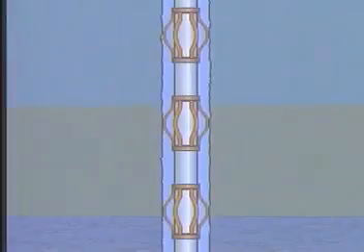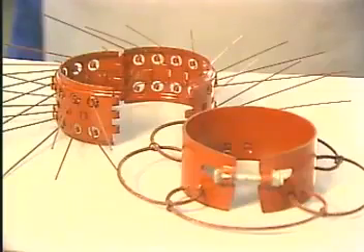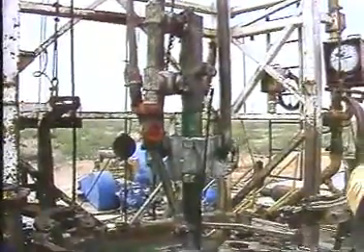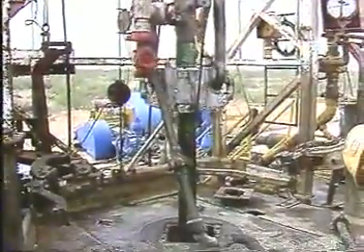Such mud channeling is the predominant cause of cementing failure, and much of a good cementing procedure is focused on preventing this from occurring. Several techniques, which are often combined, are pipe centralization to allow uniform displacement of the mud by the cement, pipe movement, either reciprocation or rotation with scratchers to improve displacement in enlarged hole areas, and the high displacement rates and turbulent flow regime mentioned earlier. A good cementing procedure will also provide the following directions.